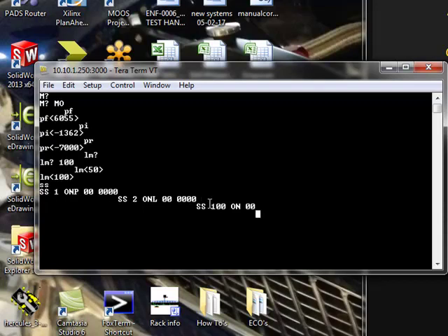So we expect that, for example, if a VSWR condition occurs, it will occur at the top level of the system ahead of the last resort protection that is set up in the booster. So depending on how severe the condition may be, you may only get a top level fault flag set, as opposed to having a lower level booster flag set for the same parameter or fault condition.